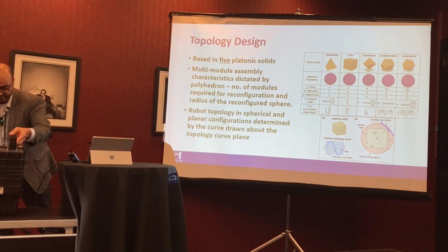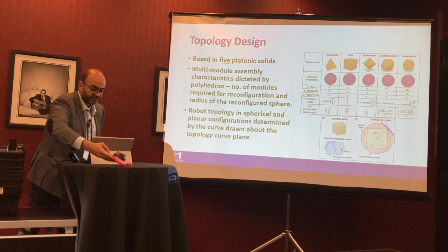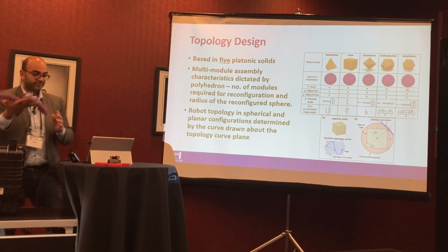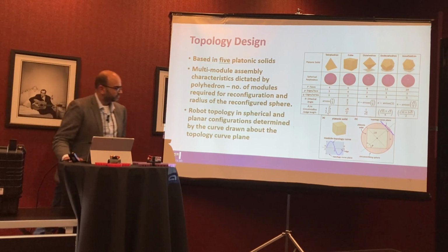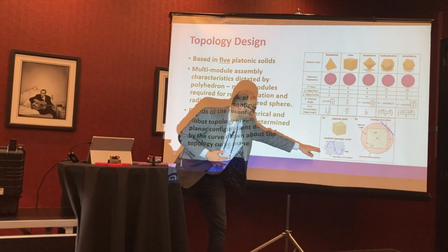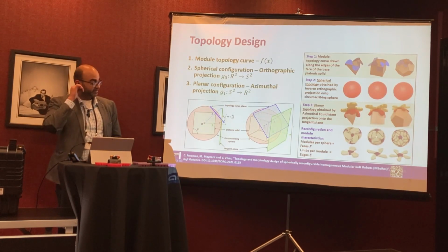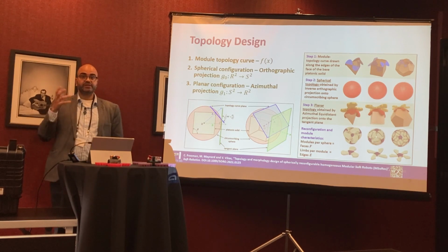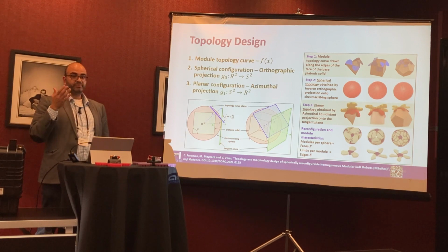So for example, this is a 3-limb robot that can reconfigure into a spherical ball. And I'll show you in the next slide too. But like this is a 4-limb soft robot that can reconfigure into, again, these. Geometrically we only found out the function needs to be odd, but we optimize it for a sine family. Here the important concept was that we are using concepts of geometry, projections, that we typically use in building maps.